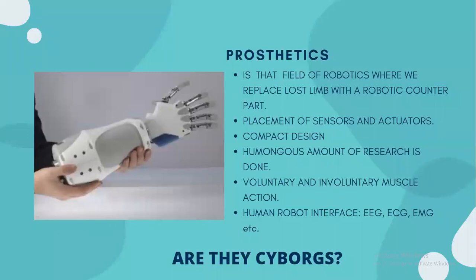But one important thing about these robotic systems is that they should have a good data acquisition system. We are talking about replacing involuntary or voluntary muscular actions with the help of a robotic counterpart. In that case, you need to extract electroencephalograms, or maybe electrocardiograms, or maybe electromyograms. Definitely electromyograms. In that case, you would have to use a data acquisition system to extract EMG information, and then you can maybe train a machine learning algorithm or a neural network, and then pass the output to the actuators.